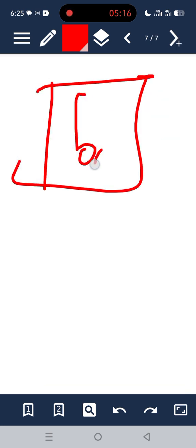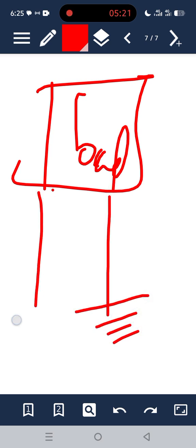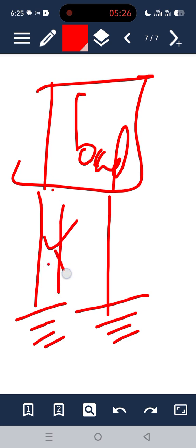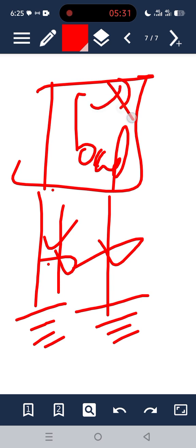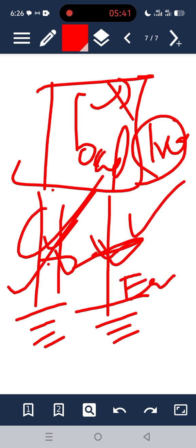So let's look at it this way. The load is here. The load is grounded, and you are also standing on the ground. As we have seen from the first test scenario, some current is flowing through you, and some current is flowing through this cable. So in case this one is touched by a live wire, the electricity is going to take the path of least resistance through the earth cable rather than your body. I guess you understand now basically where the return current goes. It doesn't disappear in thin air, rather it travels back to the source through the earth mass.